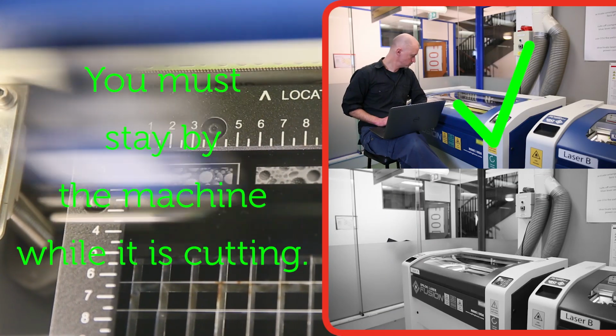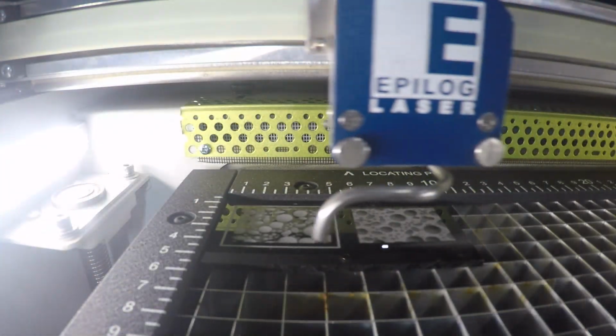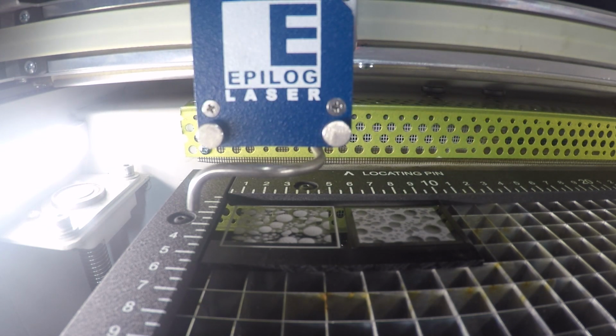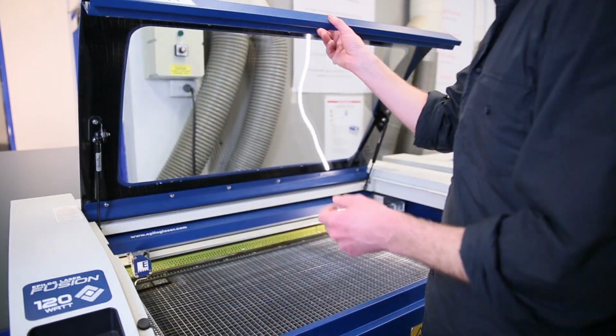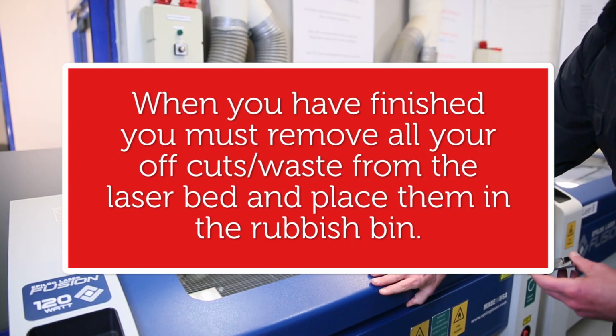Make sure you stay by the machine while it is cutting. Once the cutting is complete, the laser head assembly will move back to its home position and beep once. This is telling you that the job is finished. Leave the lid down for at least 5 seconds and let any gas get extracted. Then take out your job as well as your offcuts and place any unwanted material in the rubbish bin.